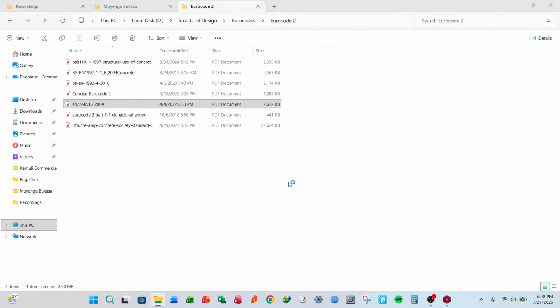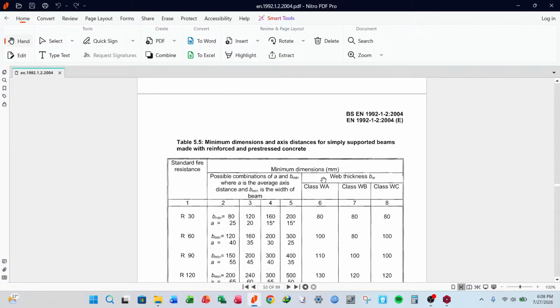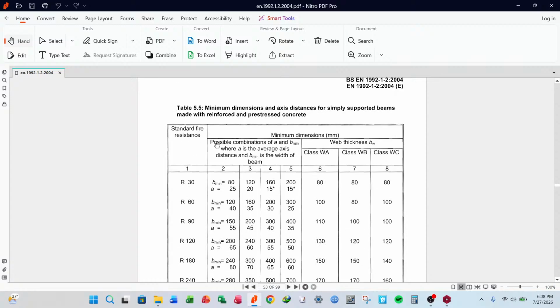Okay, where we have minimum dimensions of structural elements. So the cover due to durability is measured from the outer face of the concrete member to the outermost edge of the reinforcement, for instance a stirrup if it's a beam, what we call the nominal cover.